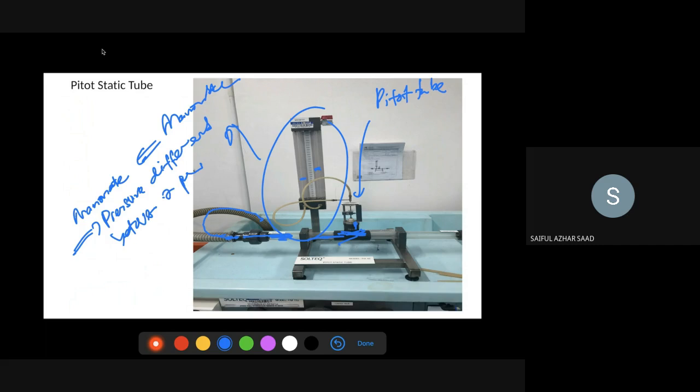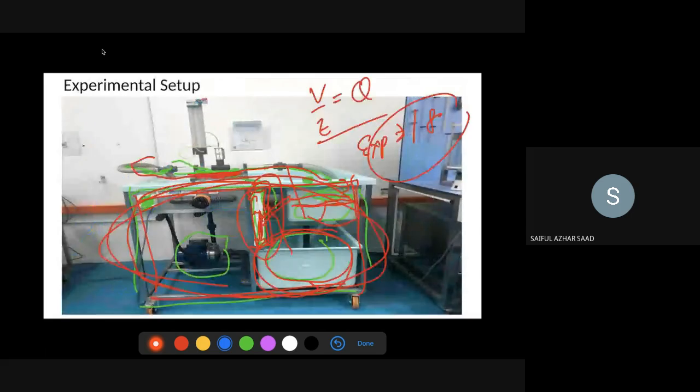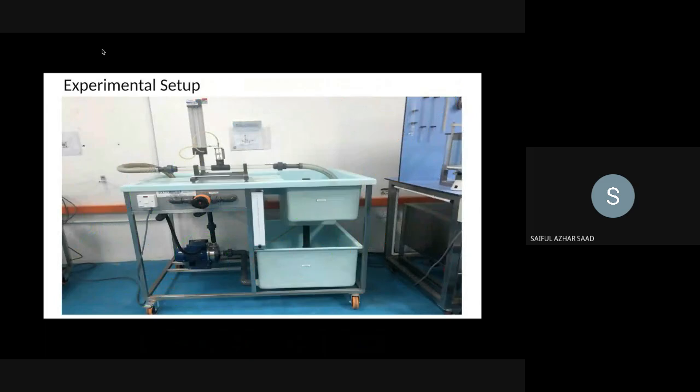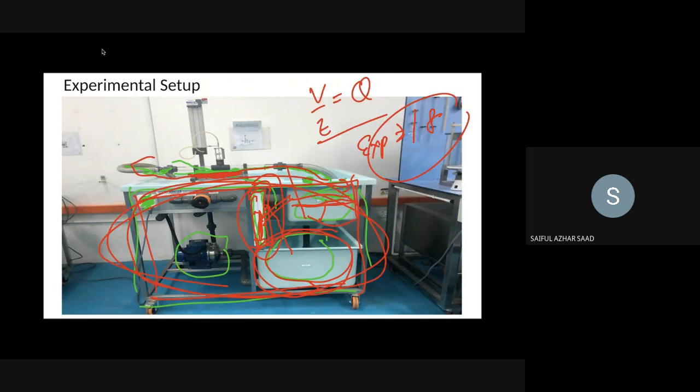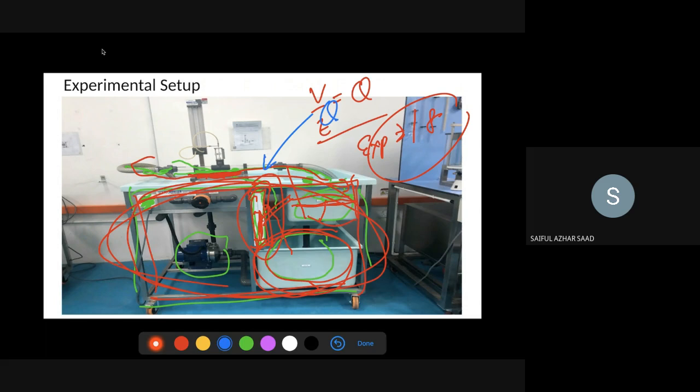All right. Your job is, number 1, to calculate the flow rate Q by using the hydraulic bench. Number 2 is to record the height of the water for point A and also point B. Let's say you fix the time, time equals 30 seconds, and then you measure the water level over here.